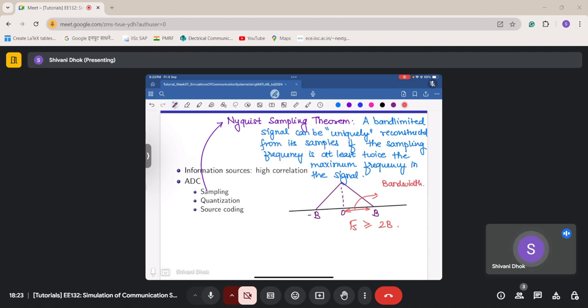After that, we looked at what is known as quantization. I won't go into detail in the interest of time. I'll just mention what all things we did. In quantization, we looked at three things. First one was a simple Lloyd max quantizer. This minimized the mean square error, and we had to iteratively look at the thresholds and the range over which we would be minimizing. So it is an optimization problem that we need to solve iteratively.